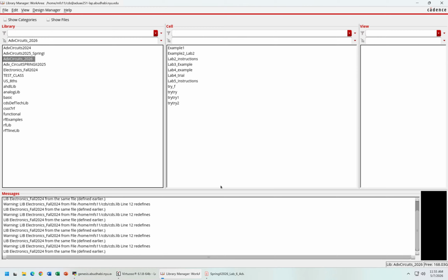The moment the frequencies are in a no-pass region, the filter starts attenuating those input values. These filter responses are in the form of the frequency response of the system, and to run these kinds of simulations we have to use AC simulations.